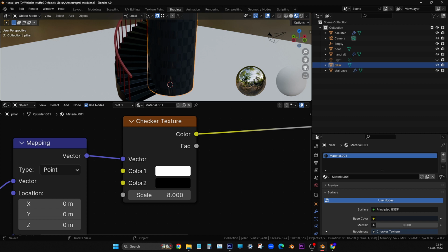You can duplicate the spotlight with Shift D and then keep one more. Rotate this one and make it face towards the object. That yellow color dot inside the light, you can also use for rotation. It will turn the direction of the light.